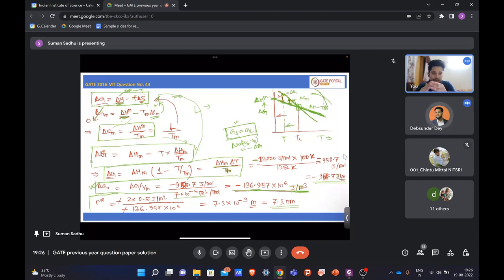And that delta T also depends on what type of nucleation is occurring, either homogeneous or heterogeneous. For heterogeneous nucleation, you have an extra surface, like from the inclusion you can get one surface, from the mold wall you will get a surface. Since you already get a surface for the nucleation, the energy requirement will be less.